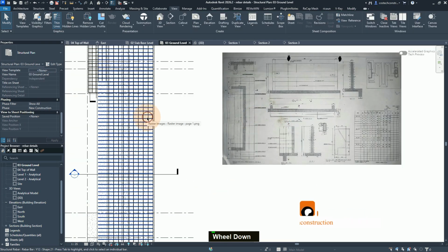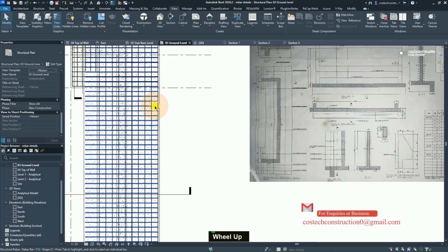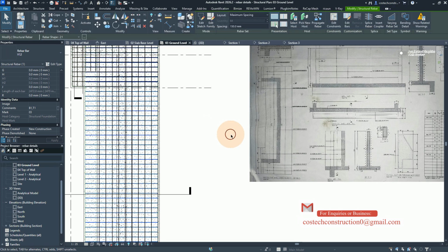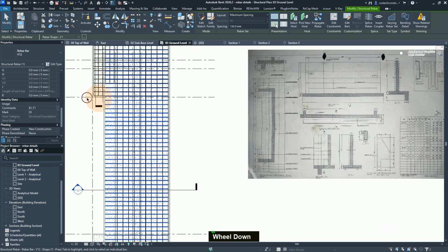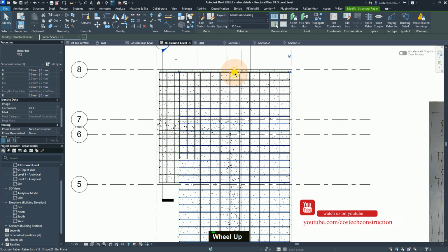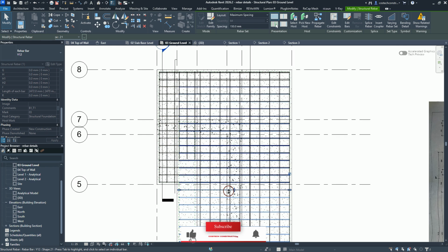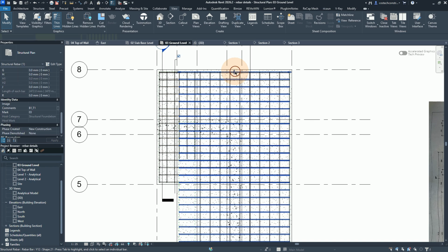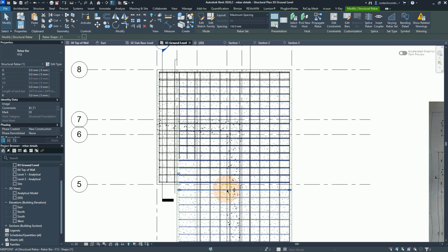Now we can select on any. We'll pick on the first one like that. And from here, we'll need to change the span. So from here, the top one, I will select it, then drag it up to this point here. I'll click outside, select the other rebar set, then drag it to align to the previously moved one.